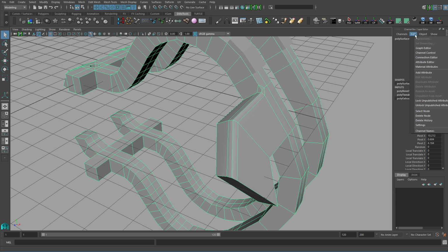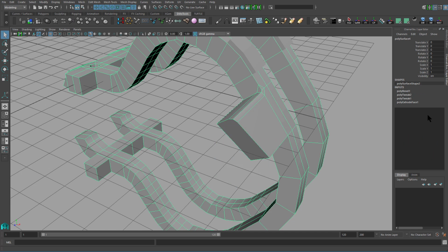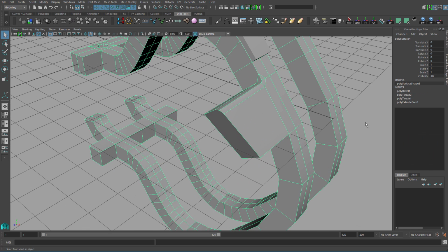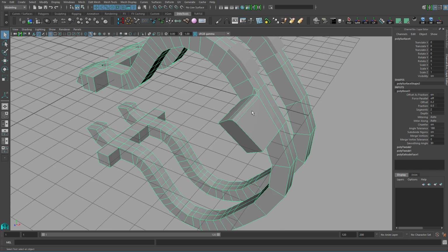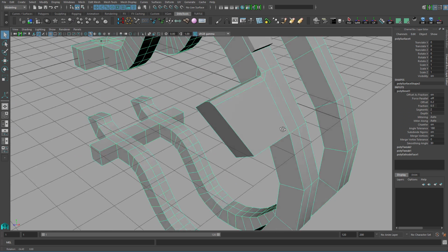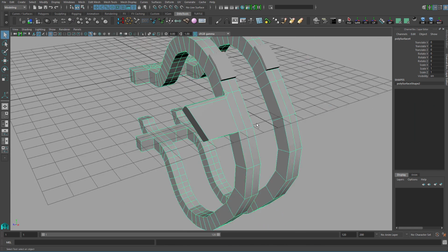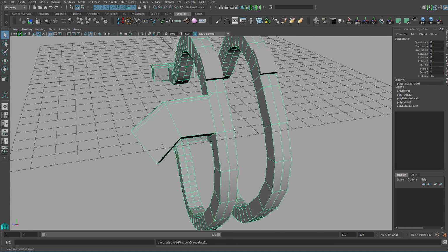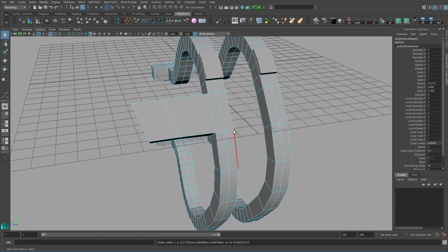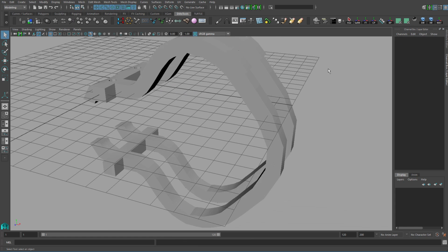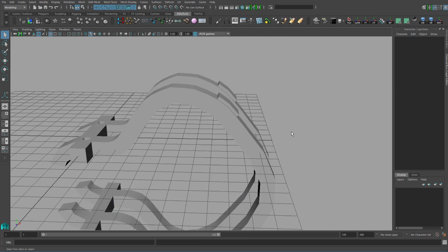Let's try that again. Now that extrusion disappears, and the bevel you did later will still be there. It's a very convenient way to manipulate your input. Let's delete history, or let me just go back again. Alt Shift D to delete history, very useful.